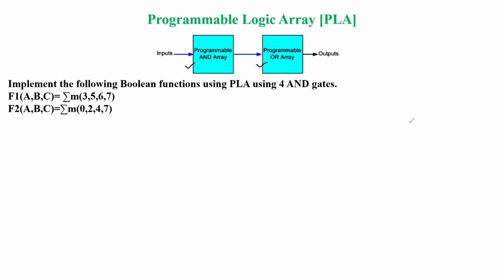So we should be careful in this. When we are going to draw here and here, we don't have the option to choose a decoder, since all the combinations of the variables will not be represented in case of PLA. So decoders are not useful here completely. That's why we are going to use the AND array only, and another thing is that it is programmable also.